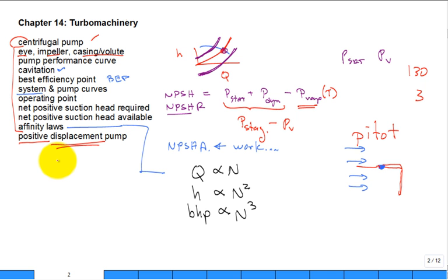But we just noted that they have a particular characteristic: you want this flow rate, and they'll work really hard to give that flow rate, no matter what head they have to provide. And so their curves are very steep. They have a slight backward curve to it, and then they break because it's too much. But basically, a constant volume flow rate application is a great positive displacement pump application. There it is. That's that chapter. Did I miss anything?